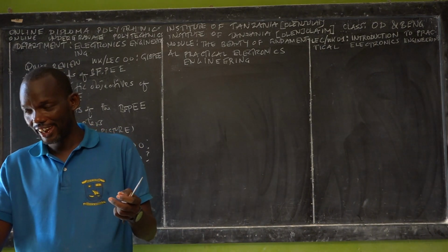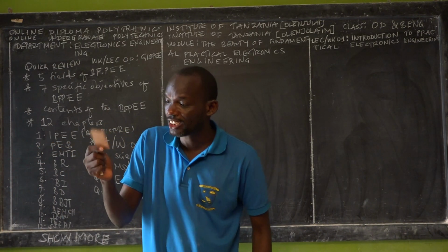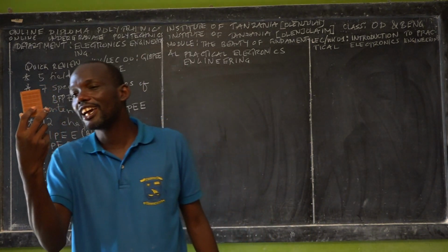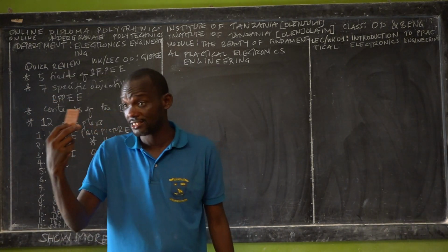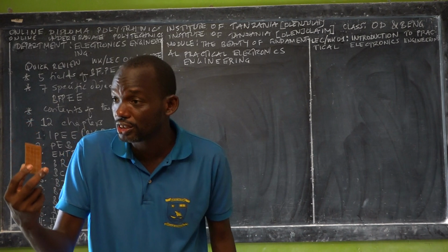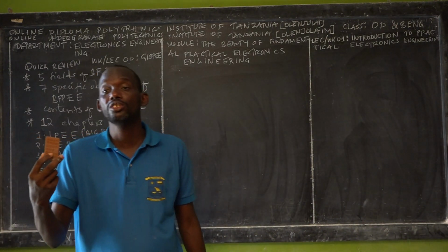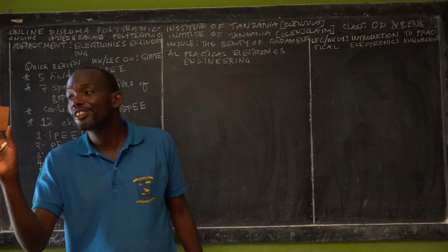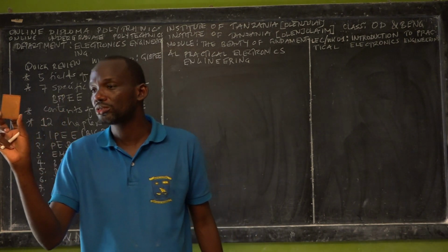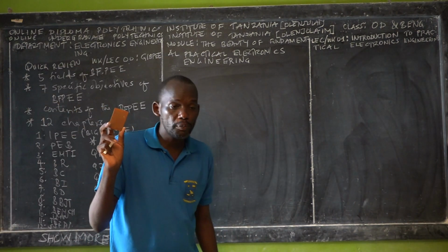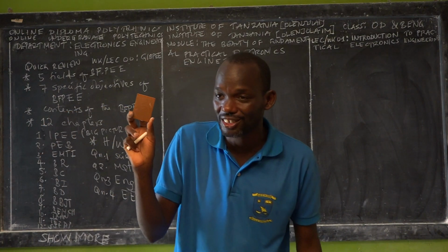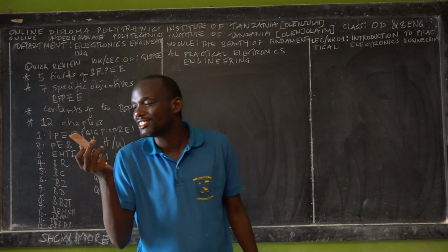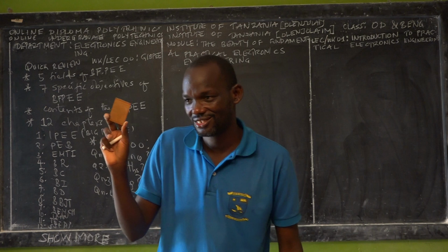Again, once we come into this working bench, which is called the variable, it has 2 sides, right? One side is plastic, the top side. Plastic is a bad conductor of electricity, so we don't expect it to have connections on the top surface. But the bottom surface contains plastic and some copper holes. Copper, is it a good conductor of electricity or a bad conductor? Good conductor of electricity. So it means that our connections will be focusing on those copper holes.